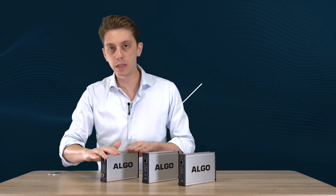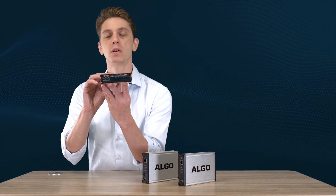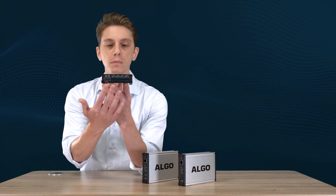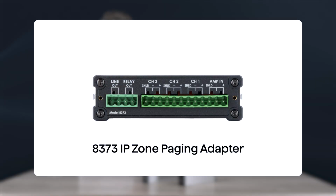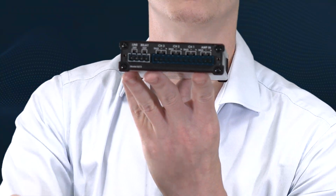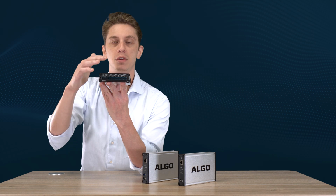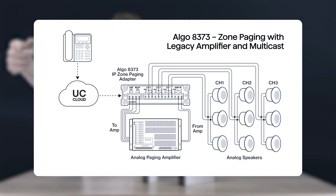And last but not least, the 8373 terminals are going to look quite a bit different here. The main application here is to integrate with amplifiers as well, standard analog amplifiers. The difference is this is going to let you zone out your amplifier, right? So we're going to have a line level output coming out of this paging adapter. It goes into the amplifier, your 70 volt, 100 volt output where you normally have your analog speakers connected.